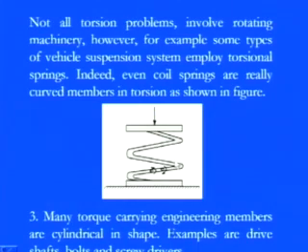You can see these things. These are the key features, and if you want to design those things, always think in terms of the spring, because a spring is simply based on stiffness. What you see is the force per unit deformation under the action of the shearing part. So we need to consider how stiff the spring is, that means how stiff these spring parts are and how many coils there are. This is a very important figure, and then you see what twisting moment and shearing stresses occur in those kinds of springs.